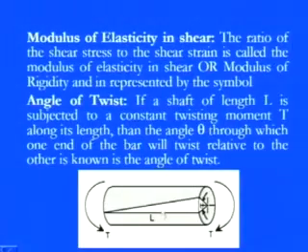So if a shaft is of length L, which is subjected to a constant twisting moment T, then the angle theta will always give how much distortion there is. Through this, one end of the bar will twist relative to the other end, and this angle is known as the angle of twist, because wherever the shearing action is there, the angle of twist is forming. If we can measure the angle of twist, it will give you how much distortion there is,